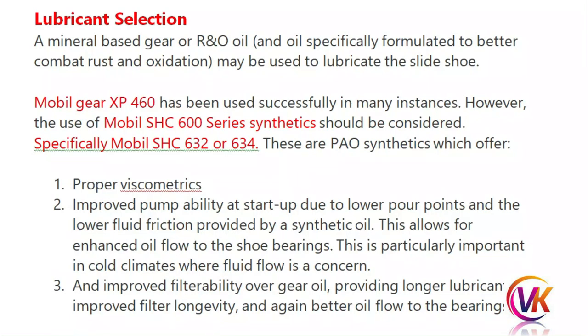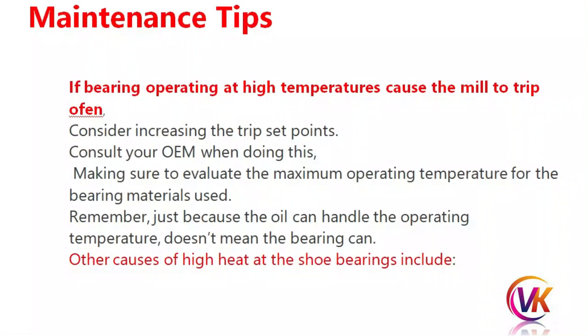Third, improved filterability compared to gear oil, providing longer lubrication life, improved filter longevity, and again better oil flow to the bearings. Maintenance tips. If the bearing operates at high temperatures, it can cause the mill to trip too often. To avoid this, there are some points.